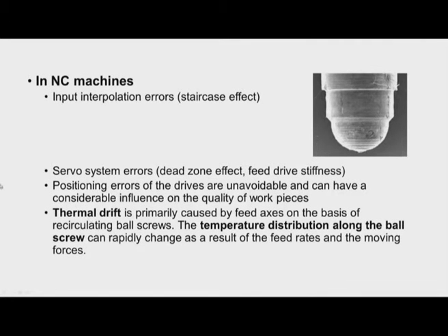Now, in case of NC machines the input interpolation errors will be there. Because of that there will be a staircase effect on the workpiece like this. If we observe this picture, here we can see there is some staircase effect. Okay. So, now other reasons for dimensional changes are servo system errors like dead zone effect and feed drive stiffness,